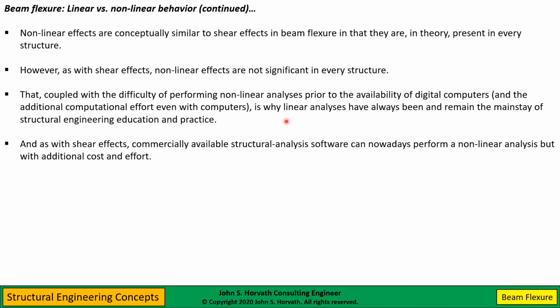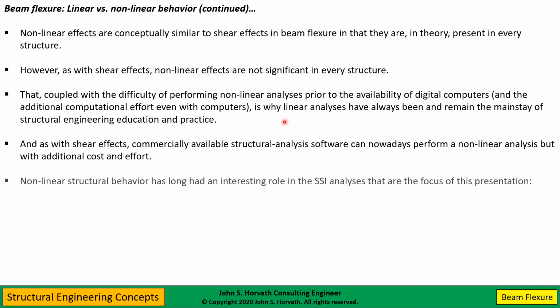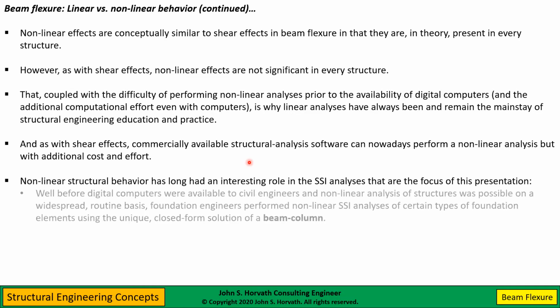Now, the point is we could do nonlinear analyses these days, but yes, I do understand and appreciate that depending on the software package, this may be an additional cost for a nonlinear module, and it does take some additional effort on the part of the design professional involved. But nonlinear structural behavior has long been very, very important to soil structure interaction analyses, which is why I'm emphasizing nonlinear behavior so much.